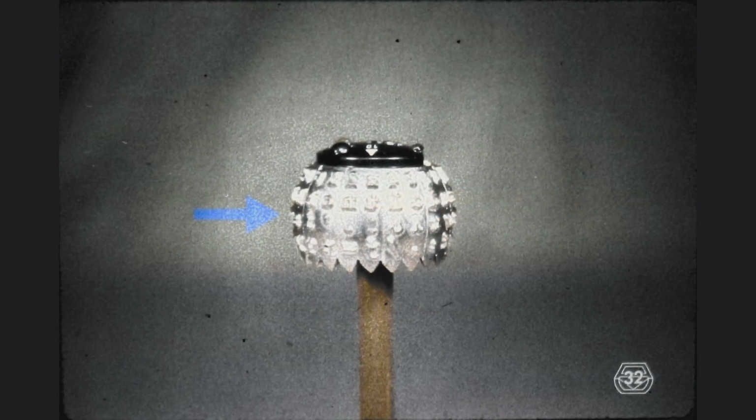Here we are looking at the element as seen from the rear of the machine, with the shift mechanism set to print small characters. Notice the position of the Z in this picture, and then the T under the Z. In order to print the T, all we would have to do is tilt the element by 1 tilt increment. By counting the letters to the right of the small letter T, we find 5 more small characters. The same is true for the left side of the letter T. There are 5 more small characters to the left of T in order to select any of the 10 characters located to the left and right of the letter Z, T, the exclamation mark, or J.